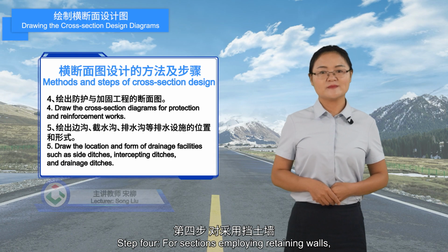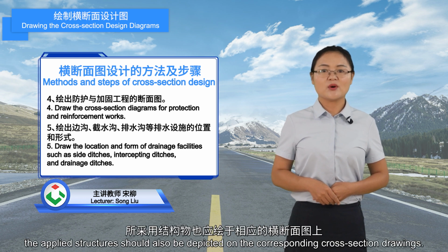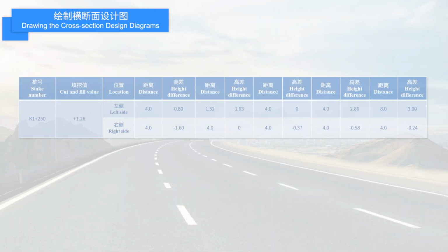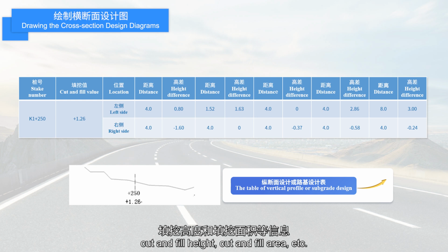Step 4. For sections employing retaining walls, slope protection, and other structures, the applied structures should also be depicted on the corresponding cross-section drawings. Step 5. Draw the drainage facilities. Finally, fill in the information such as stake number, cut and fill height, cut and fill area, etc.